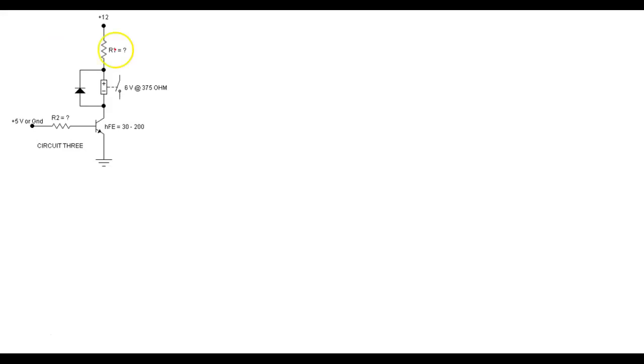So here we have a relay. What's the purpose of the diode? It's in reverse bias. We went over the lab last class. We put an inductor out there. We charged that sucker up to 12 volts. When we disconnected, that thing discharged over 90 volts. It would blow its transistor out.